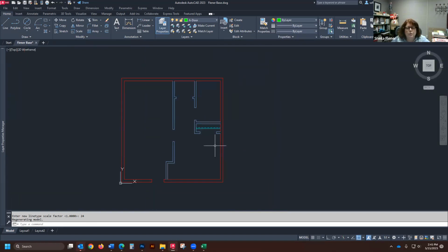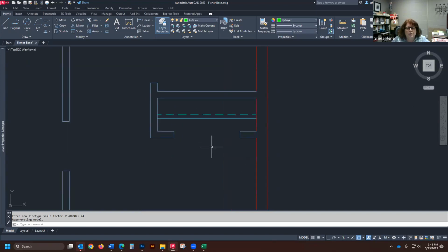Okay, so now we can work on doors. So here's our closet door. It's a sliding closet door. So we're going to click our rectangle tool. Each door is going to be 24 inches wide and 1.5 inches thick. So I've clicked the rectangle tool. I'm going to click on the screen first, drag out my cursor, and then do Shift at 24, 1.5. There is my closet door.